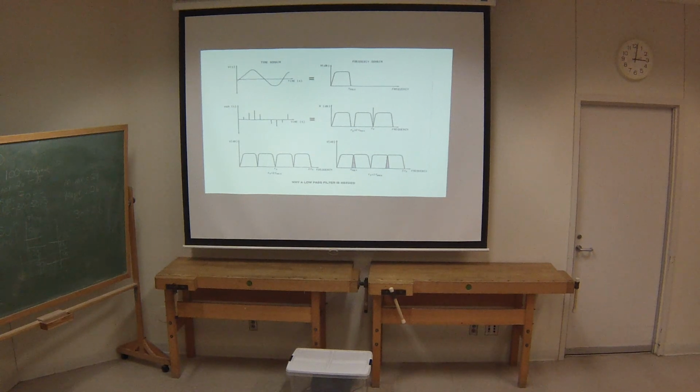So, if we're talking about compact disc, then the maximum frequency that we are interested in is 20 kilohertz. Well, 2 times 20 is 40 kilohertz, and then we need a little fudge room, and so the actual sample rate for a compact disc is 44.1 kilohertz, and it yields us an effective frequency response of 0 to 20 kilohertz.